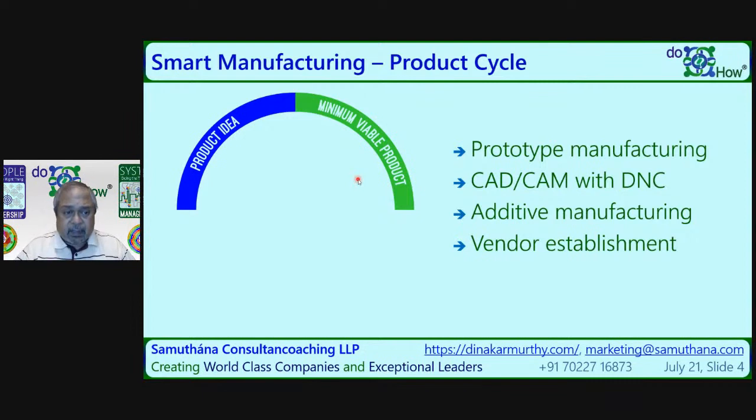Therefore, a lot of measurements are normally done. And there again, it is extremely important to collate this information, to later be able to analyze and build correlations between the end effect and outcome and the individual dimensions. A lot of smartness can be used for data analytics. It's not really big data, it is data analytics and data science, because you're trying to understand whether the diameter of the shaft has any influence on the opening pressure of a particular valve, or whether the diameter of the shaft or the clearance between the shaft and the coil has any effect on the magnetic force in a solenoid valve. Things of that kind need to be understood.